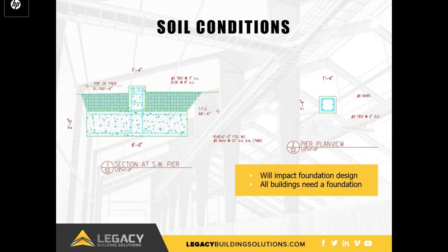The type and quality of the soil beneath the building will have a significant impact on the foundation. Soils high in peat or clay may not have the strength to support a fully loaded building. Changing the soil type is prohibitively expensive. The entity designing the building foundation should complete soil testing. An experienced building engineer will design a building foundation that will support the weight of the building on your site.